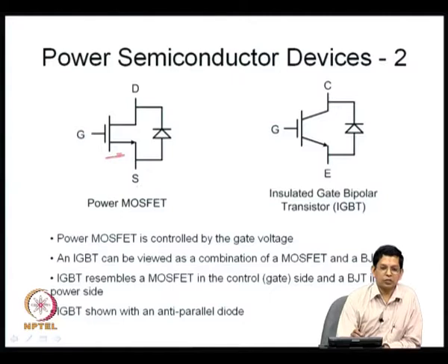You can turn it off by applying a voltage which is well below threshold, or this voltage could even be negative. So, this MOSFET is again a controlled switch which is controlled through its gate source voltage VGS. And a MOSFET typically has a body diode between its source and drain, as shown here. So, this is a complete MOSFET that you normally get for power applications.